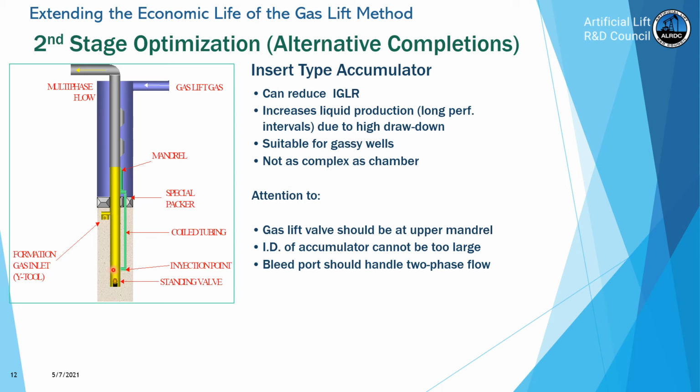So what's going to happen is that early in the cycle, while you're generating the liquid column here, the gradient here is going to be much greater than the gradient here. So early in the cycle, this standing valve will close, and we should be able to handle everything through this valve.